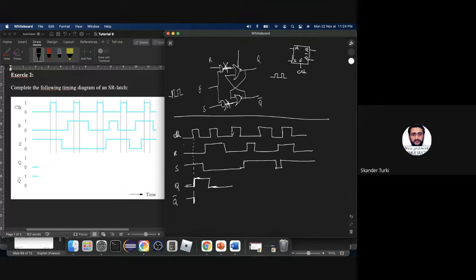So now when we have this tick of the clock, what happens? The system will see that R became 0 and S also is 0. And we have seen that this means that the system saves its state, doesn't have any modification yet. So it will stay like this until. So here we can see that the clock deactivated just before S becomes 1.